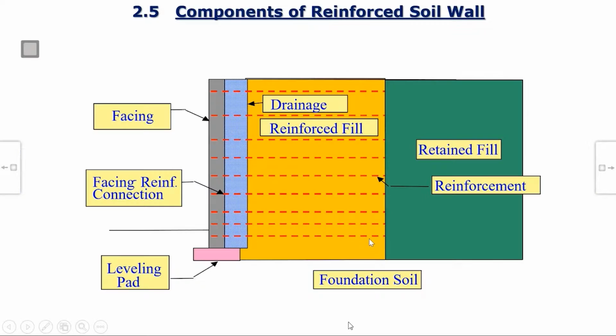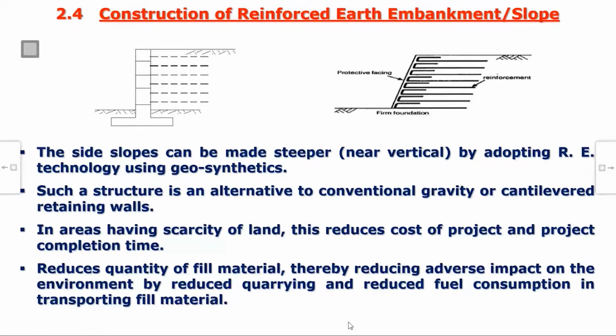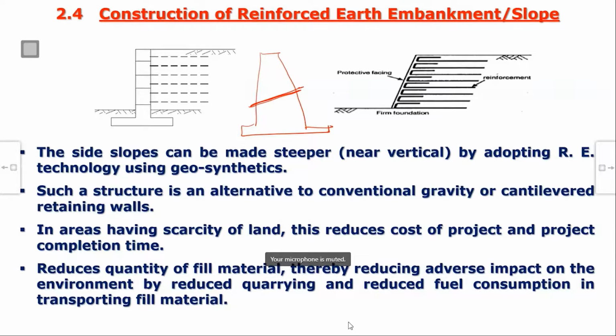And the third thing, which is not there but we'll see, is these structures are more flexible as compared to rigid structures. If this is, let us say, a retaining wall, and if some crack develops here, maybe I will try to do some grouting and all. But if it does not work, then repairing this is very, very difficult. Maybe you have to remove this whole thing and then put some dowel here and again construct this.